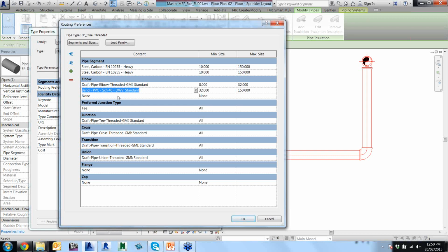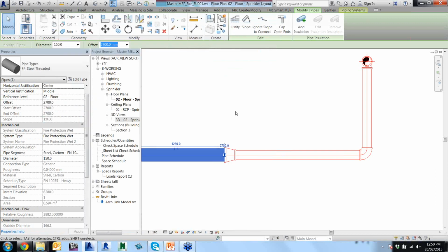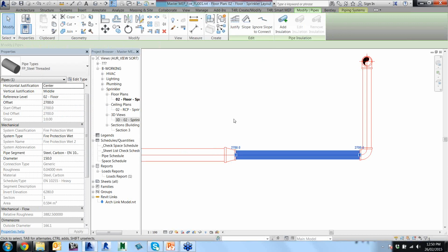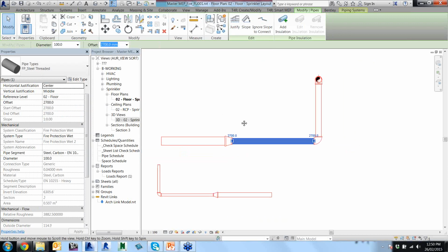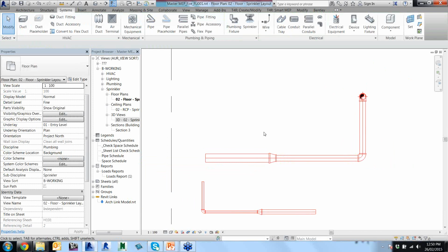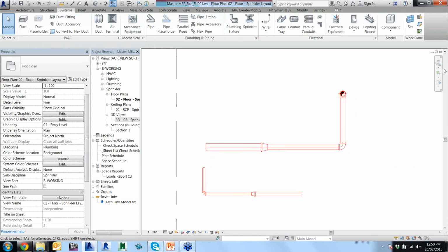a larger range, or a medium range and a larger range, and you have to continuously flick through those pipe types to actually route your pipe run, whereas this way effectively lets you use the one pipe type, and you just change the diameters as you go, and the settings in the background will take care of what material is actually being worked there. So I'll have a better example of that in a bit more detail a little bit later, where we can have a look at some of the BIM MEP Oz pipe types. Okay.